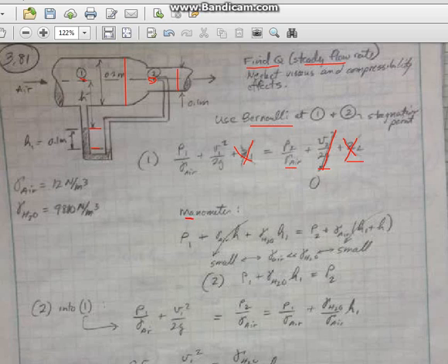But first let's look at the manometer. So we have to remember how to do the manometer equation. Let's again go from point 1 to point 2. But now we're going to go through the manometer approach, right? So if we start at 1 and we go down h, so we get gamma air plus h. That's going to be small, right? But let's just go through the motions here. Then we're going to cross over to this side, and we can go all the way up to 2 because we're in one fluid here.